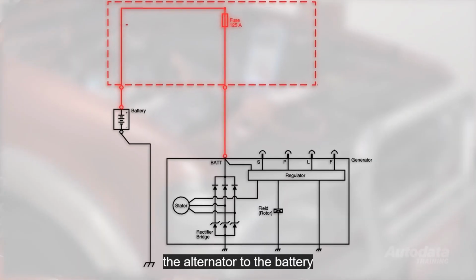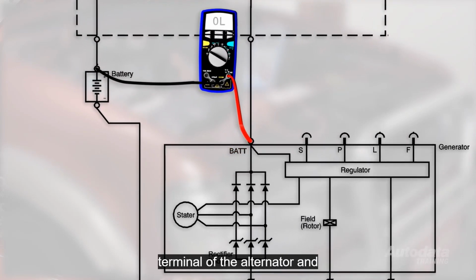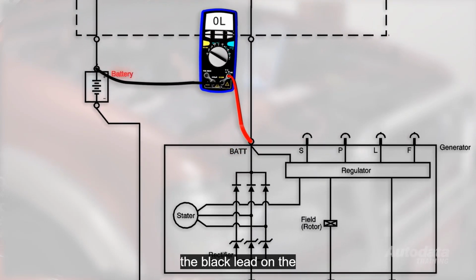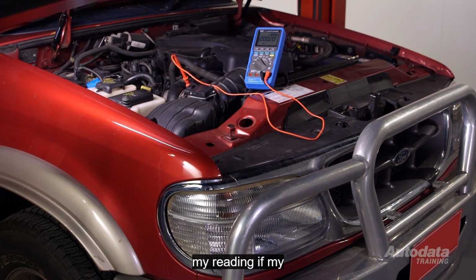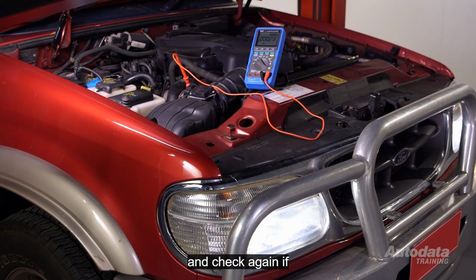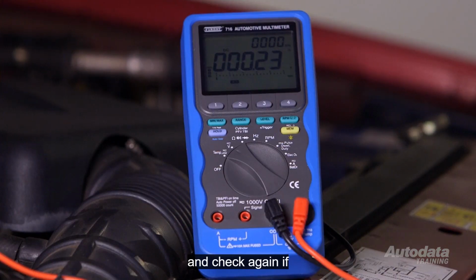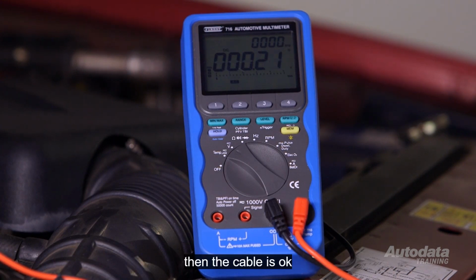To check the wiring from the alternator to the battery, I'll put the red lead on the B+ terminal of the alternator and the black lead on the positive battery terminal. Now I'll start the engine and take a look at my reading. If my reading is greater than 3% of battery voltage, I have a problem. If not, I'll turn on the headlights and the rear demister and check again. If the voltage has not increased significantly, then the cable is okay.